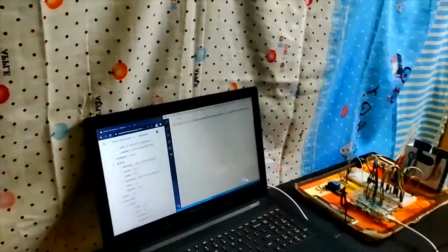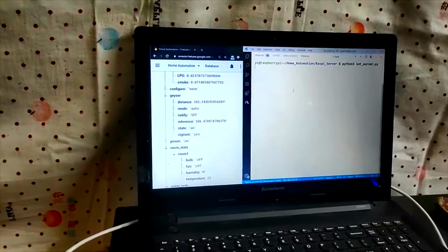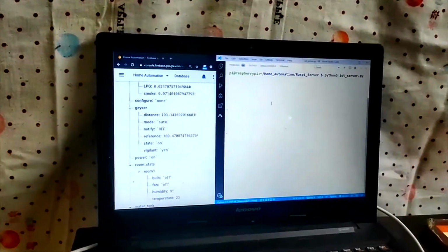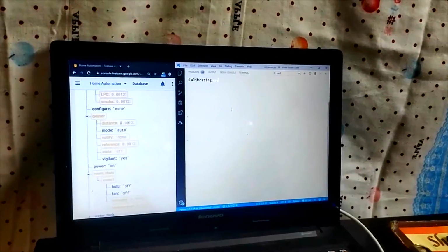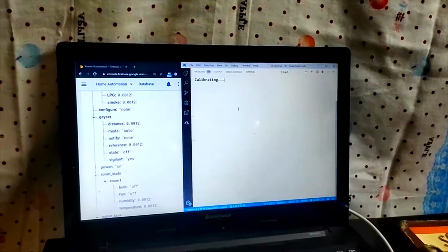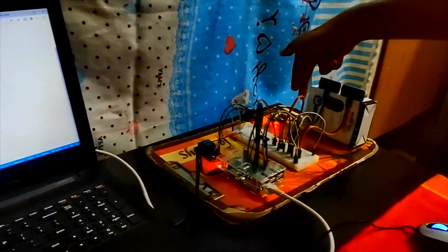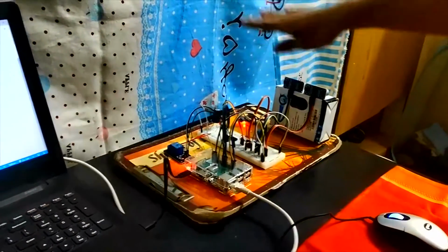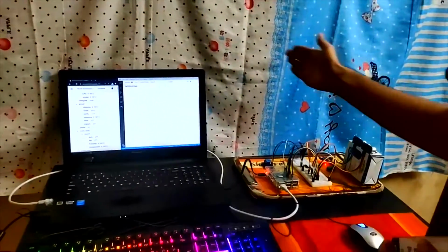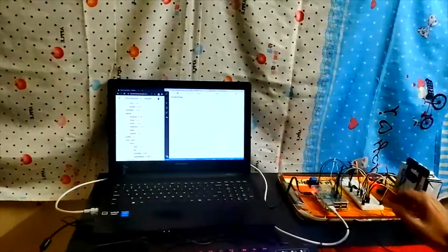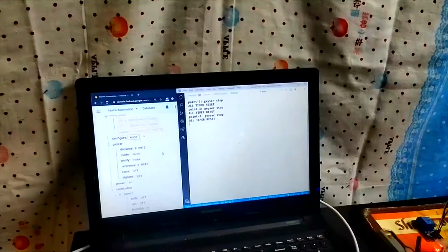So first of all, I'll begin my circuit by giving the start command, and once that happens, our circuit first calibrates itself to ascertain the normalized values for the MQ2 gas sensor and the DHT11 sensor. These values, once stabilized, can then further be used in the calculation of the rest of the circuit. And as you can see here, the database has been initialized to its original form.